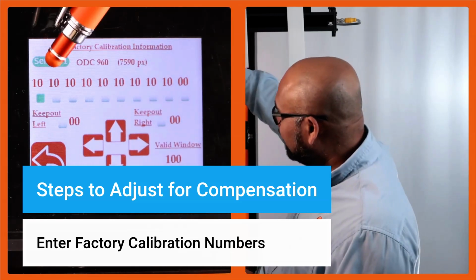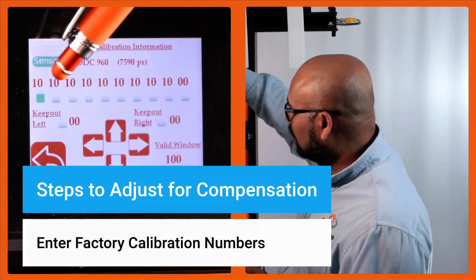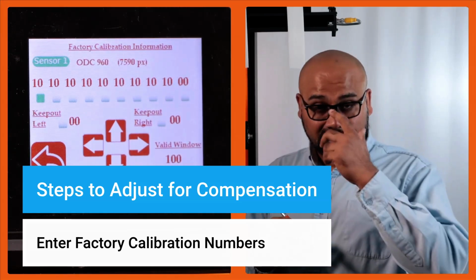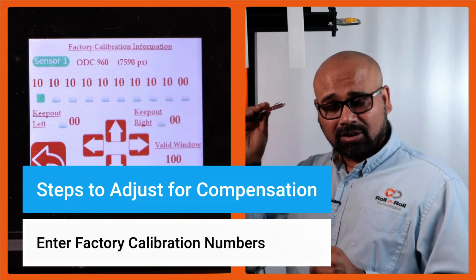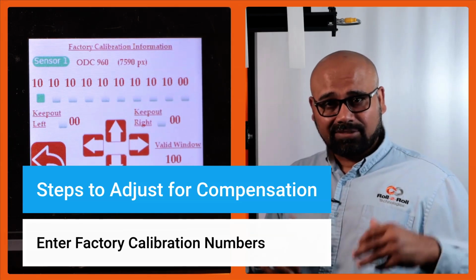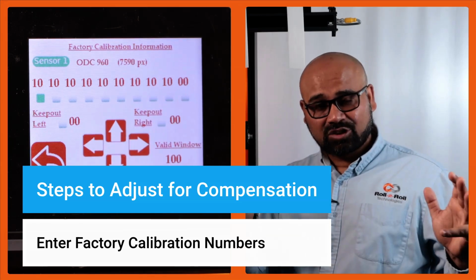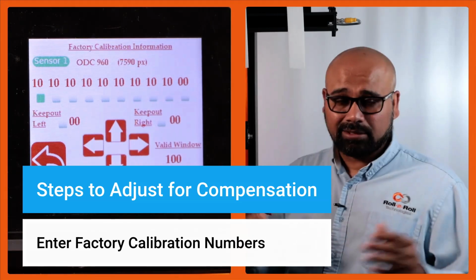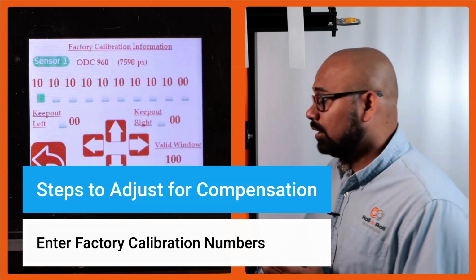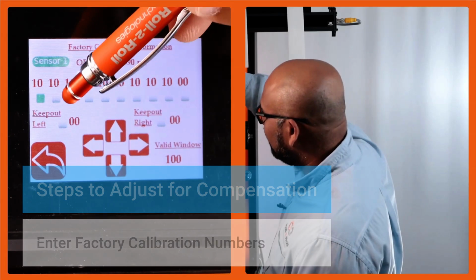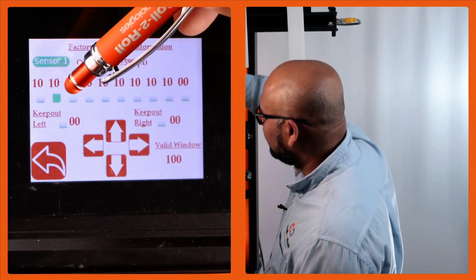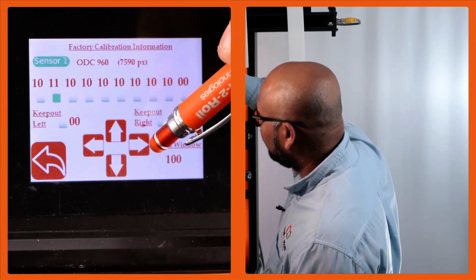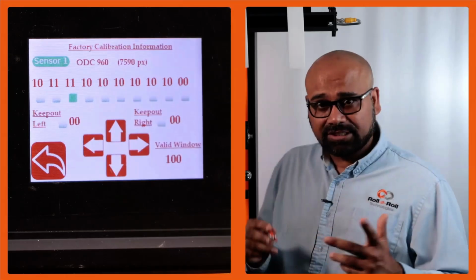There are actually 10 cameras in there. For this high resolution measurement, when we set this controller up, on the back of that sensor we will have a factory calibrated string of 10 numbers that you need to enter. It will vary between 5 and 15. For each one of them, it'll be a number. You can pick that number, and whatever that number says, you can set it there by moving the upper and lower numbers. That's the first thing we need to do.